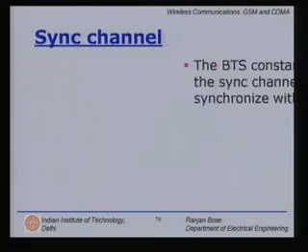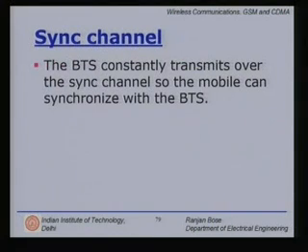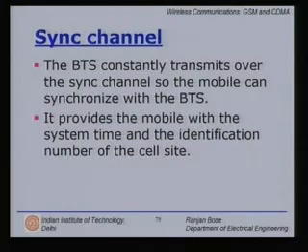Sync channel. The BTS constantly transmits over the sync channel so that the mobile can synchronize with the base station. Please note, the PN sequences are good only if your time reference is good. Even if you shift the PN sequence slightly with respect to the original PN sequence, the autocorrelation will go bad. So, synchronization is of utmost importance.